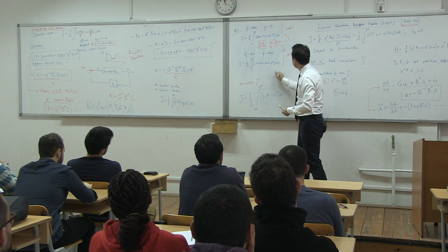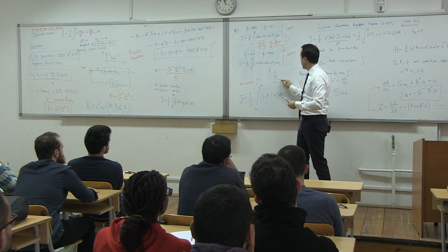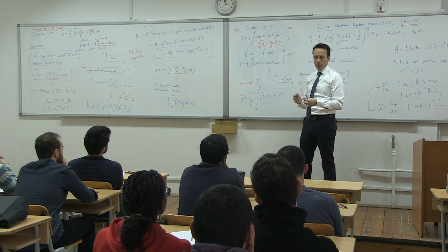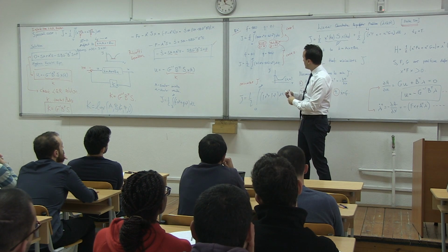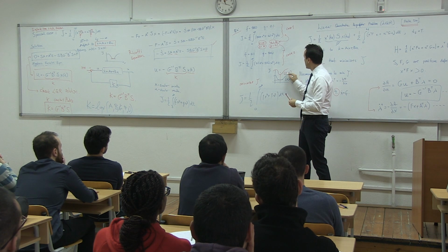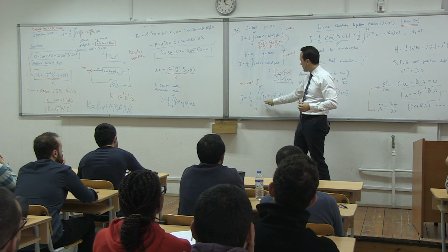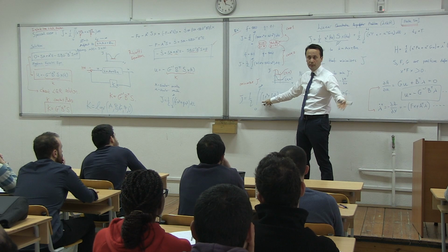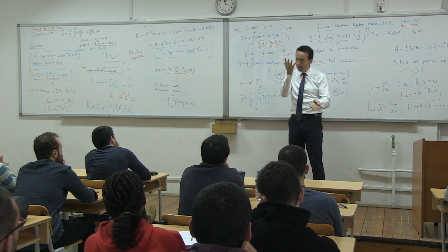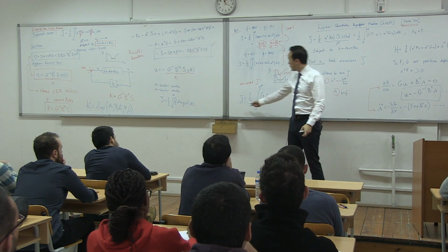So what I'm trying to say is that if you choose 1, 1, and this is j, and let's say this is x, you would get something like that, and this is your minimum. And this will correspond to a certain pair of x and u. Okay? If you make this 1000, 1000, then j will look like that, and it will still correspond to the same pair x and u, although the j will be larger. And the optimization problem will not change if you multiply this with 1000 or 1 million or 0.1 together. Understand that? What's important is the ratio of f and g. How you compare f and g. Because at the end you're trying to minimize j.